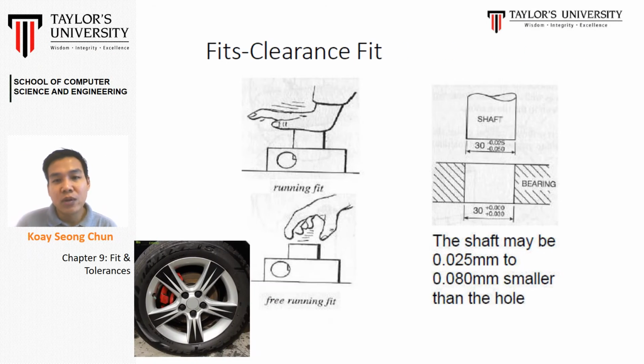First one, what is a clearance fit? The clearance fit is usually used for a part that we always need to remove and install. So we need something with a loose fit, which means we can easily just fit it onto the shaft. We can easily install it into the bearing here.